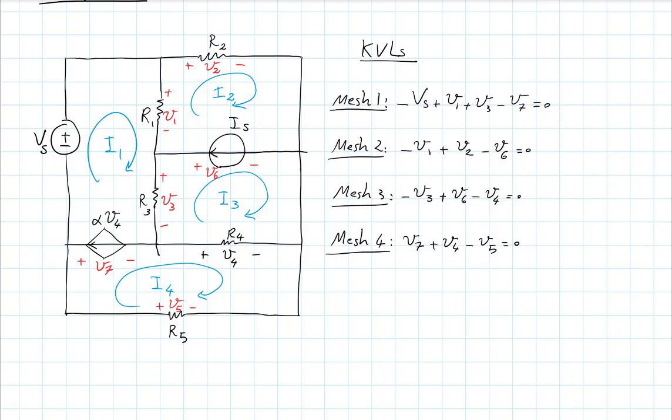The next step is to replace these voltages in terms of the element currents and eventually the mesh currents. So now if you look at V1, for instance, little V1, if I had this element current, little I1 here, little V1 would simply be R1 I1. But what is little I1 in terms of big I1 and big I2?